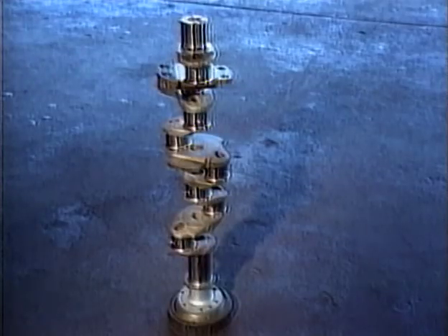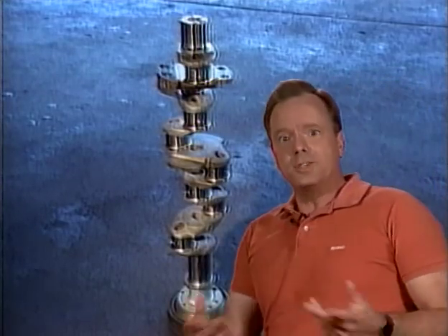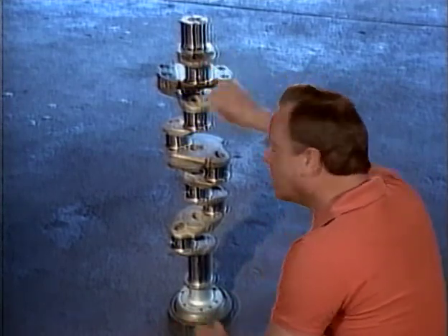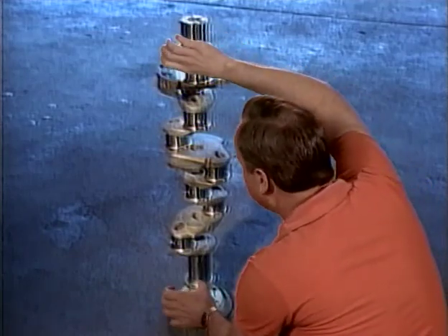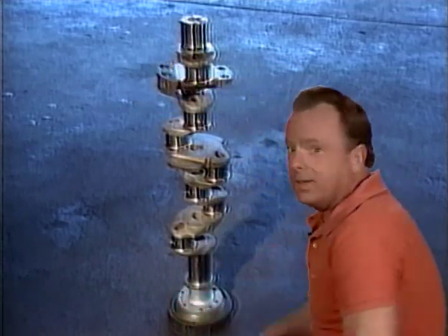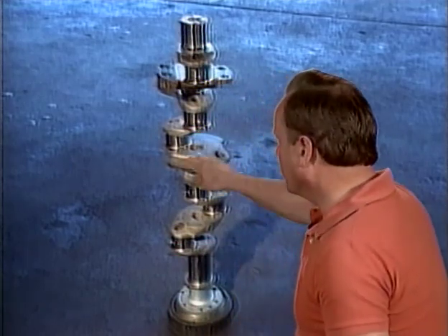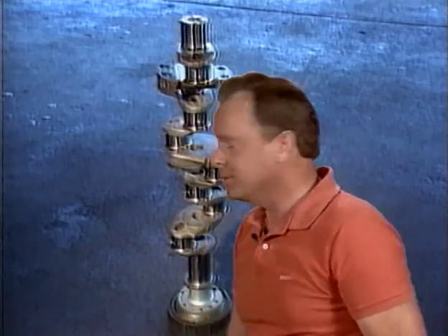Now let's you and I talk about crankshafts. The FAA wants you to know if you're examining and inspecting a crankshaft, you should use extreme care in checking for straightness, and they call that run out. If you hold the crankshaft at the ends and rotate it around, it kind of wobbles. It has run out, they call that, and there are tolerances for it. Where do you find the run out tolerances for a crankshaft? The answer is the manufacturer tells you. The current manufacturer's maintenance manual, or the manufacturer's instructions for continued airworthiness, tells you what the run out tolerances are.